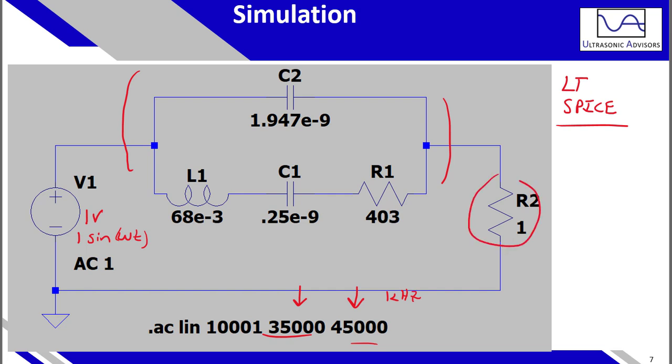This resistor here I just have as a point of convenience. It's used to measure current, although this program can directly calculate current without a need for a current sensor. I just put this as a realistic example of perhaps measuring the voltage response and hence being able to measure current going through our piezo resonator.